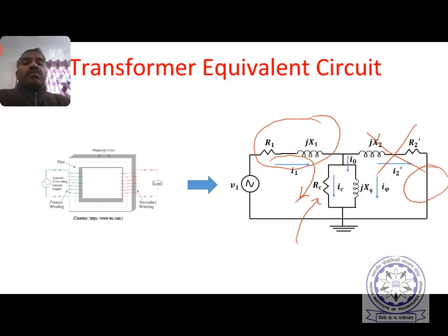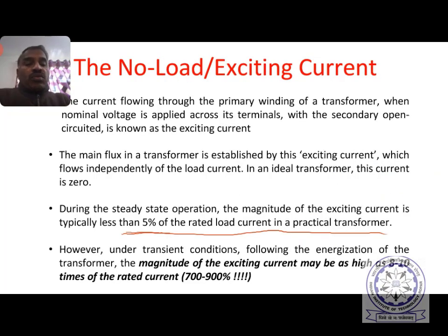Because the calculation of Rc is based on the no load test, right? Therefore, whatever value is calculated at rated voltage corresponds to hysteresis losses, eddy current losses, and whatever losses occur inside the transformer. So this is about the no load current.